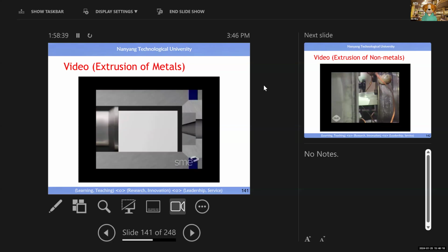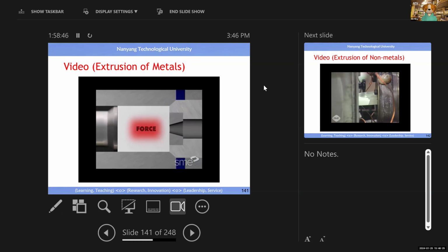Force increases before extrusion begins. Upon breakthrough, the force declines as billet length decreases until a minimum force is reached. As the billet ends, the force rapidly rises again to continue metal flow radially toward the die.